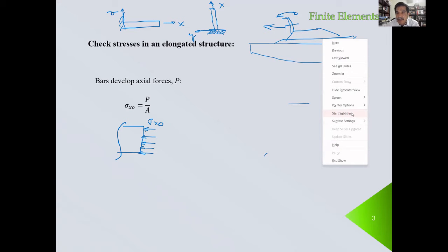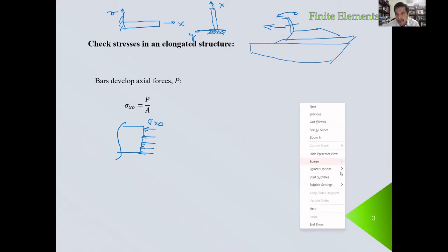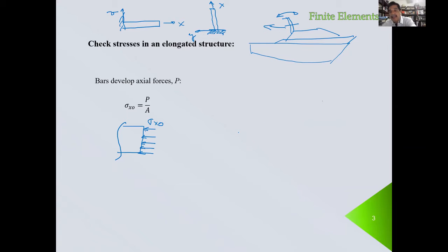Now, in a similar way, we can consider that there is also some weight outside the vertical direction of the mast. And in that case, we're going to have some bending. And we immediately remember that if we get the bending moment, Mz, this bending moment will generate a normal stress distribution, which follows this expression.